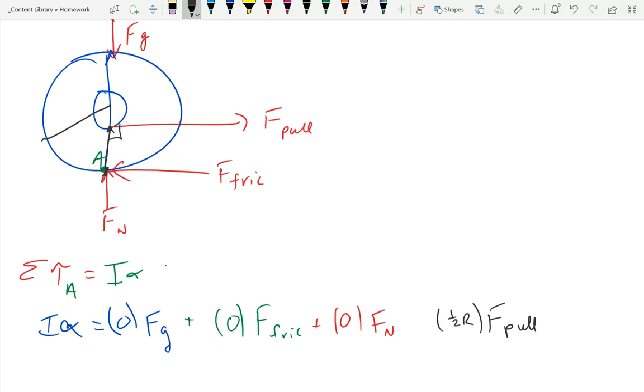So there's 2 methods. Sarah, what's your method? Sarah looks and she says, would that force make it rotate in a clockwise or counterclockwise direction about point A? And I would go with clockwise because here's point A. The force is above it and pulling to the right, so it's going to make it go like that. And so that's the way that Oksana and Sarah have been doing. It's going to make it go clockwise, and clockwise is negative.